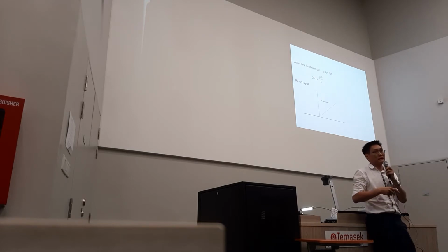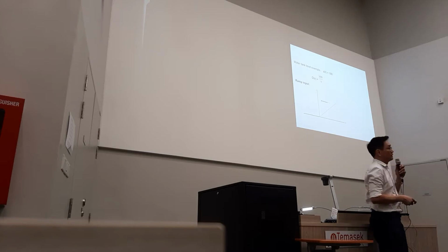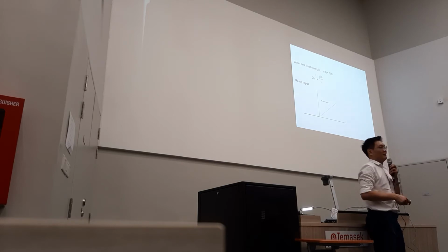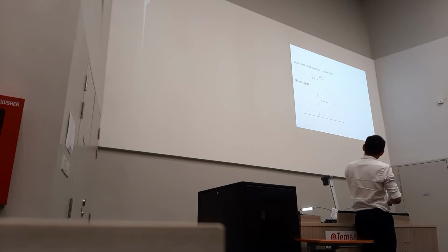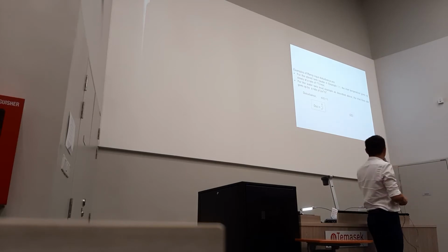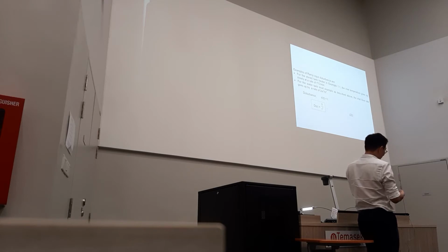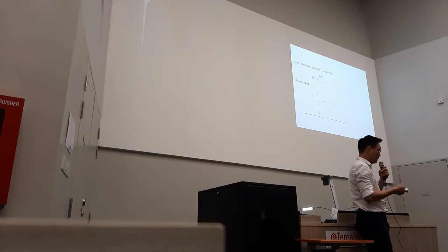Each of these disturbances has a Laplace format. For example, this disturbance in this format is for, the ramp? 1 over s is what? Oh, unit, the step. This one is for step. The ramp is the next one. The Laplace for the ramp is this one. The previous one is 1 over s, and 100 is just the value of the step disturbance, okay?